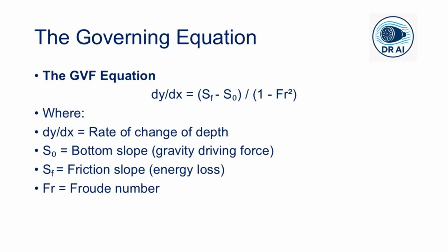dy/dx is what we want to find. It is the rate of change of depth with distance along the channel: is the water getting deeper or shallower as we go downstream? Another term is S_0, which is the bottom slope. It's actually the driving force, the component of gravity pulling the water downhill. We know this from our channel geometry.